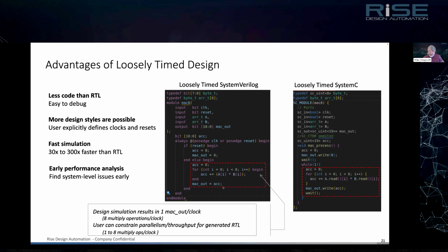What we're going to see is that with high-level synthesis, I get to decide how fast this multiply accumulate loop gets implemented in hardware. It could have anywhere from one multiplier all the way up to 8 multipliers in parallel. So I get to tune the performance using a design constraint, and the tool takes care of all the low-level details. And pretty much, these descriptions are the same.